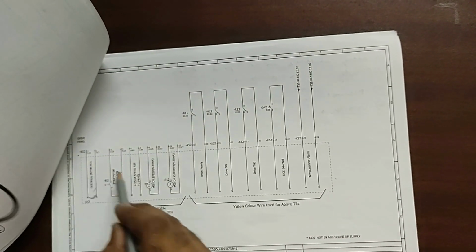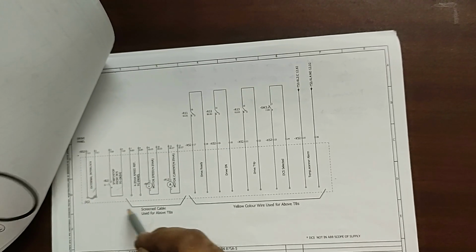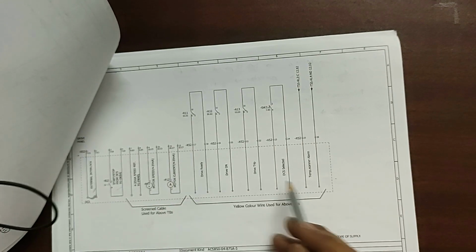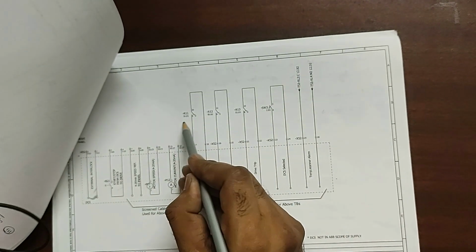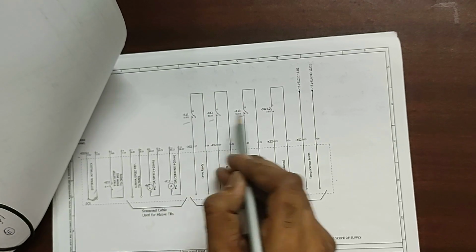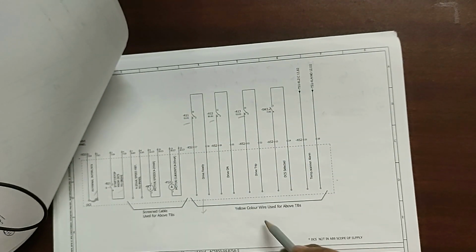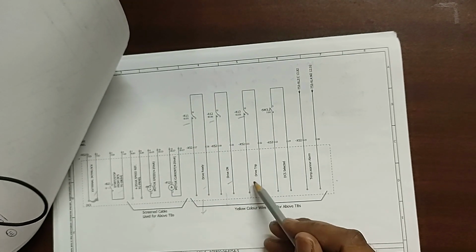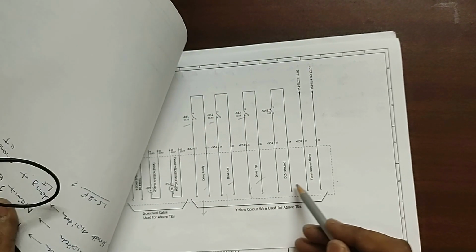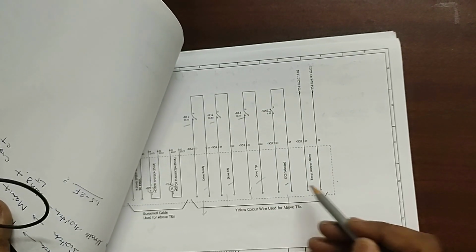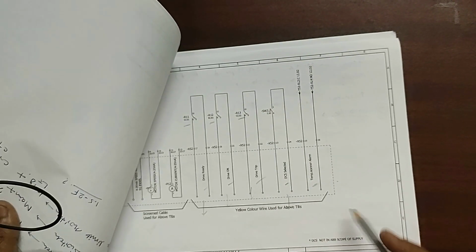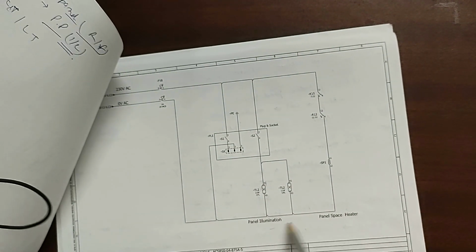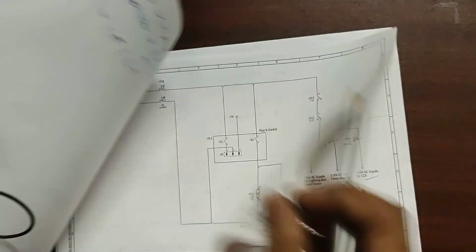Next is X52, what we have seen earlier, input command, and this is reference output, drive running trip condition. This will again, 11, 12, 13, go and feed to the PLC, telling whether the drive is in ready condition, on condition, running condition, or in trip condition. DC is selected, it will again go back to the panel, temperature alarm if required. If not, we can skip this part. This is illuminating lamp and all, you can just check it. This is not that much important.